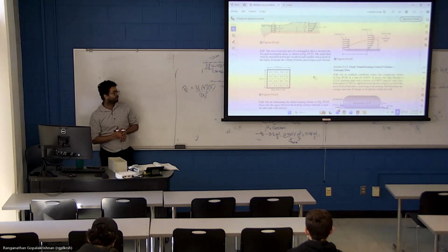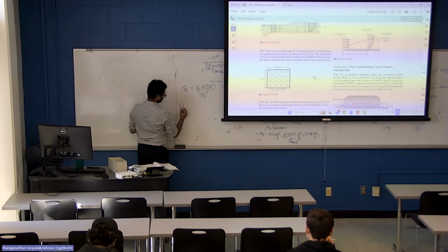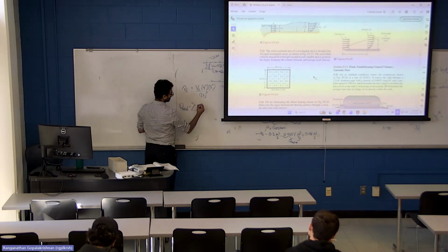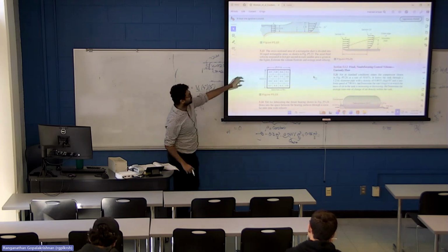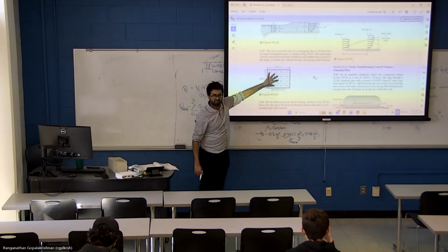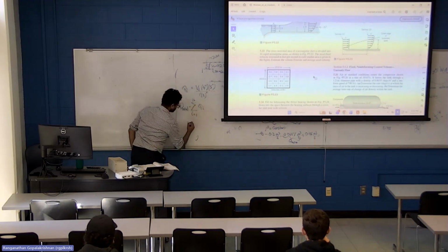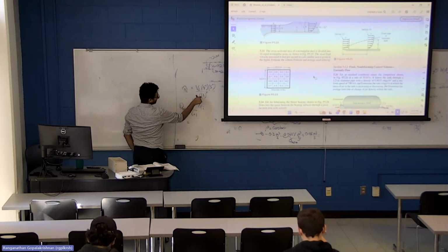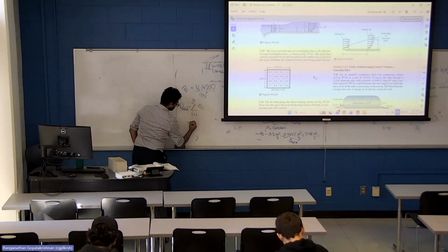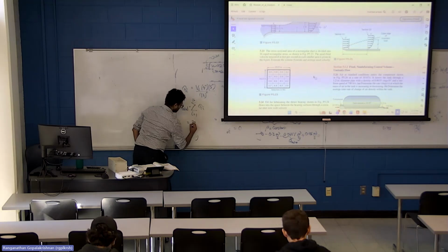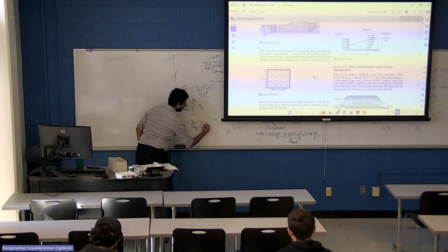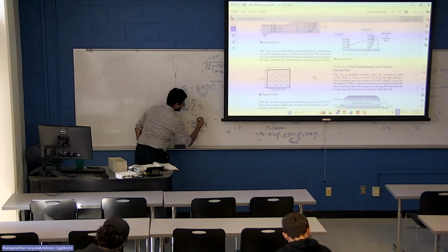Yeah. So if I want the total flow rate, Q total, that will be summation over each segment, and there are 16 such segments, right? 16 segments, right? So this is nothing but 1/3, and then 20 divided by 144 multiplied by sigma Vi for all the 16 segments.